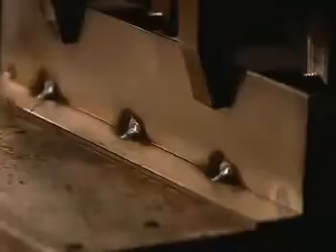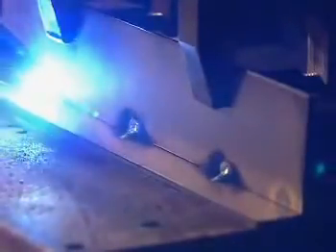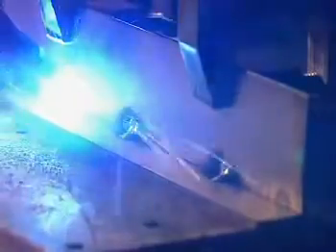AccuPulse gives operators superior control over the weld puddle, reducing spatter and cleanup, ultimately saving time and money. In automatic applications, AccuPulse improves welding over tack welds, where the arc length can adapt rapidly without stumbling and causing spatter or tip burnback. AccuPulse reacts so quickly that it increases power immediately and keeps the arc above the tack to maintain productivity and weld quality.